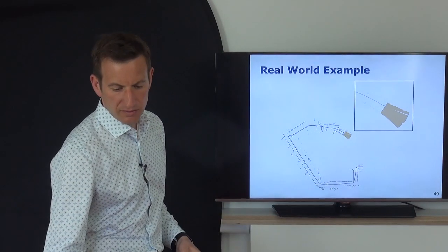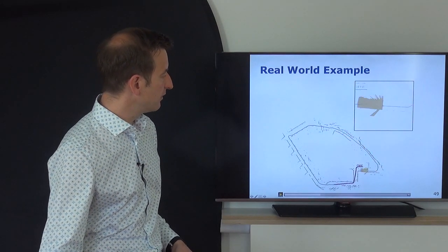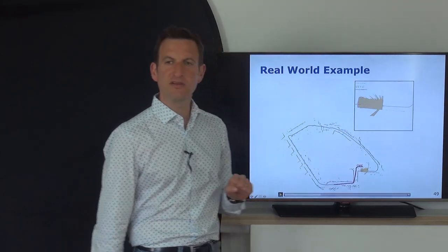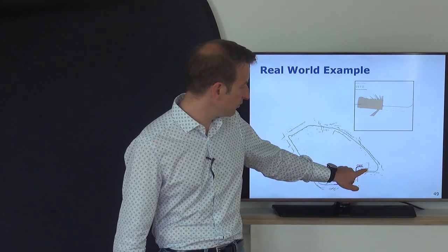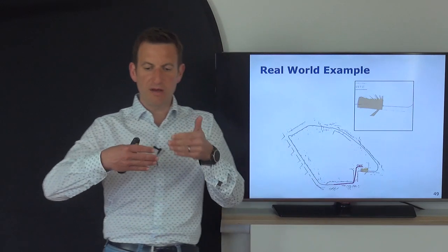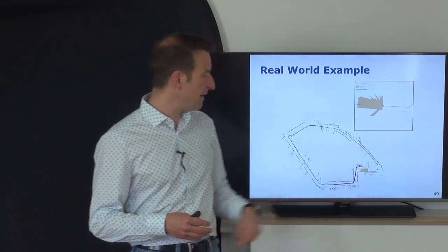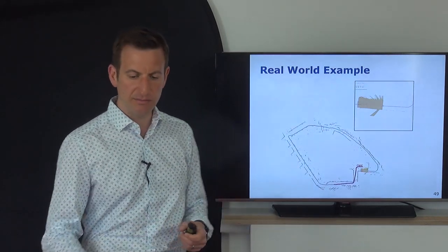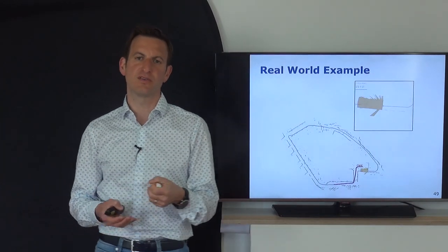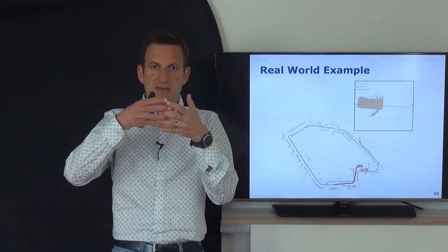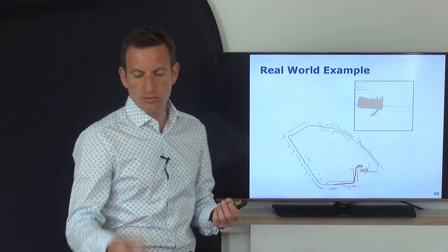What you will see in a few seconds is that the robot comes back to a previously seen place. It's maybe a little bit hard to see in the video, but if you zoom in, you can see that there's a certain mismatch, a small offset between the map built when the robot was starting and the map built when the robot was driving back. You will see this map shaking in a second. This shaking is a result of the optimization process, because we get new observations and the least squares approach shifts the nodes so that it minimizes the error introduced by those observations.